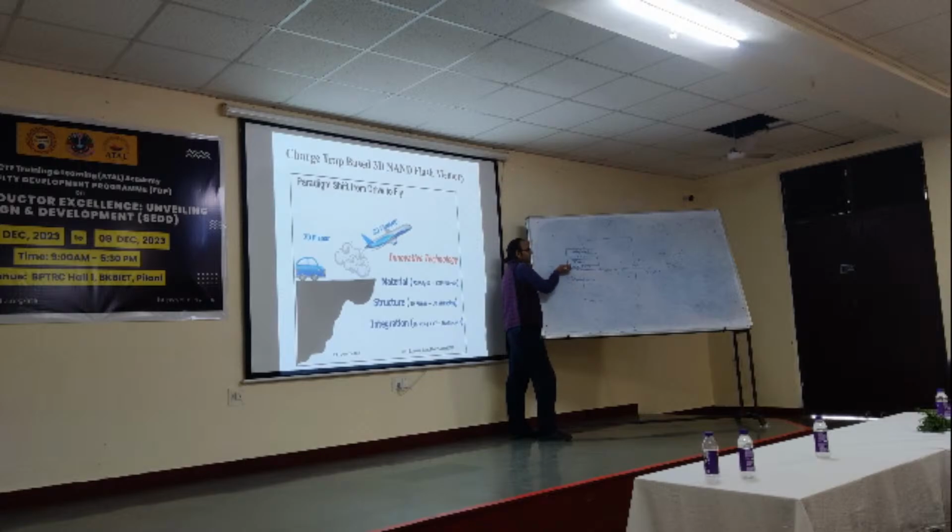So obviously, we are struggling with this difficulty in a normal MOSFET also. In a normal MOSFET also, we are always concerned about this. What do we call this current? Gate leakage. Some of the electrons cross this oxide and enter the gate. Do you know this? Leakage current means Ig is not exactly equal to 0. We utilize this concept. We trap electrons from the channel in the trap layer.